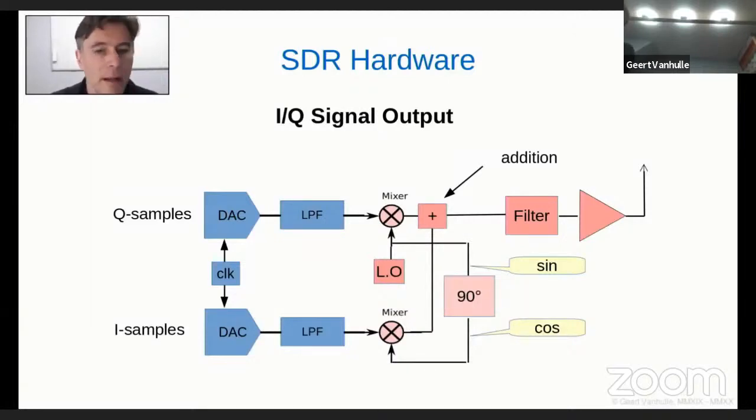But what we have here is these 4 sine and cosine terms, which produce quite a big formula of the resulting factors of the mixers. And if we do an addition of that, the reduction of this formula, because we will be able to scrap out some of the terms, will reduce the whole formula to the simple analog signal again at the output. So this is the output stage variant of what we have done on the input stage.